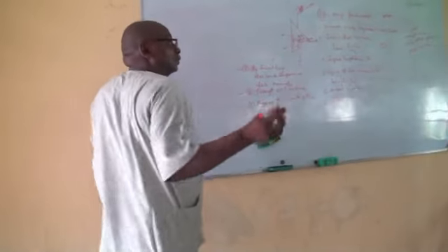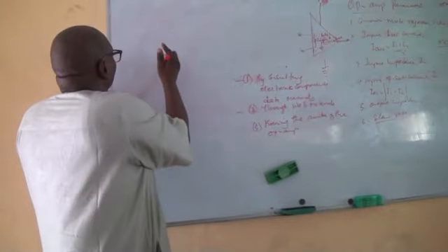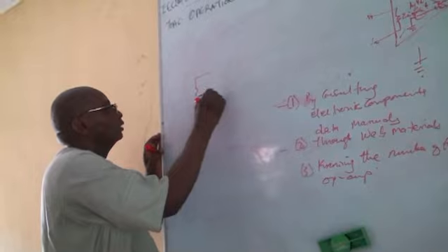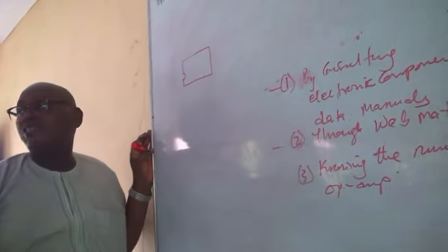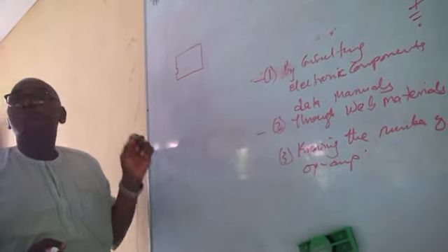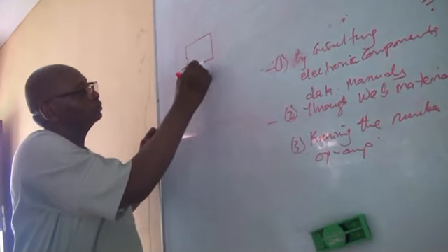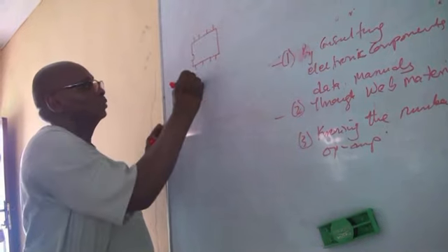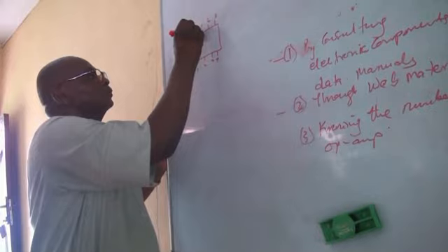Normally, we have a surface mount terminal something. But all ICs do have something of this nature. If you take any IC, you must see something like this. An opening here. And this is where you start to count 1, 2, 3, 4, 5, 6, 7, 8.